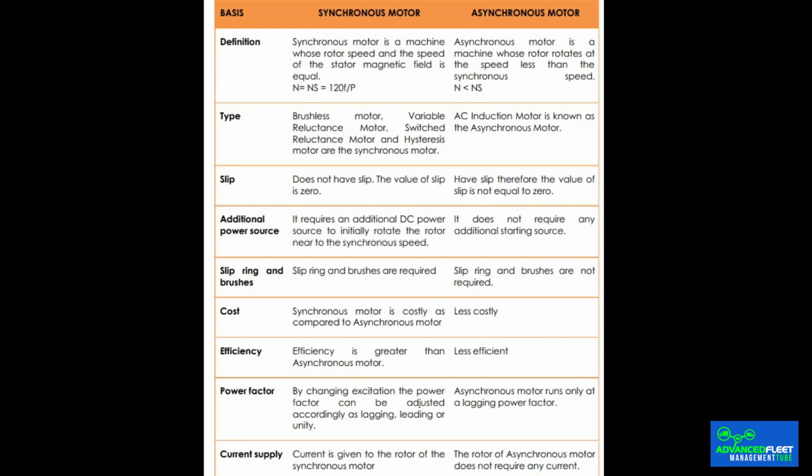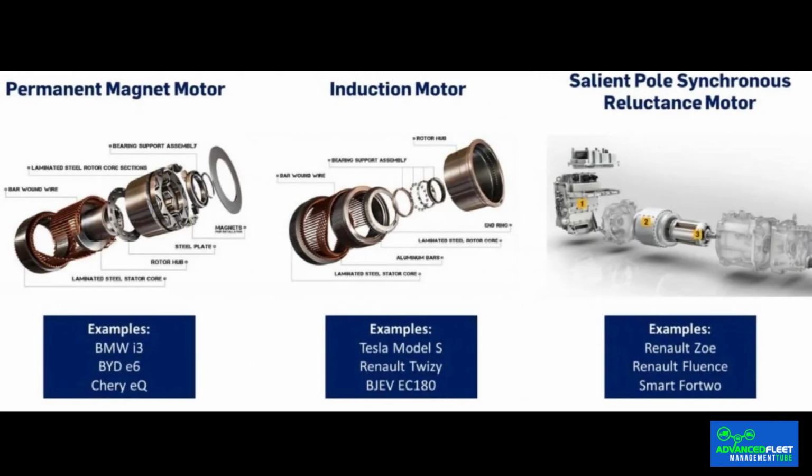Compared to externally excited motors, these allow precise control of the power of the magnet generated in the rotor, which in turn allows for optimal regulation of torque requirements at all times. On the other hand, the motors become more bulky due to the additional components required for the magnetic field power supply system. Most manufacturers opt for the use of synchronous motors, either permanent magnet or electromagnet. The choice between the two is determined by the required performance.